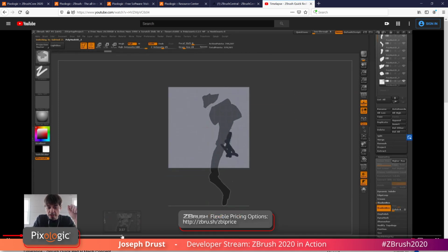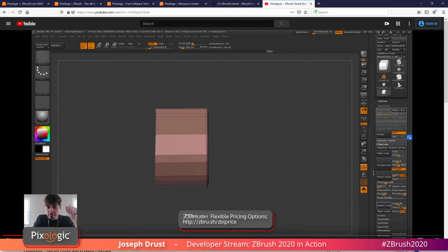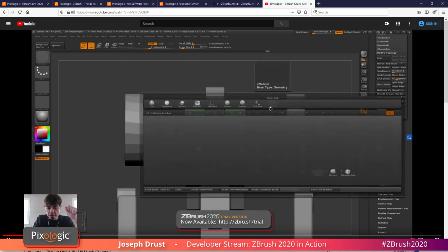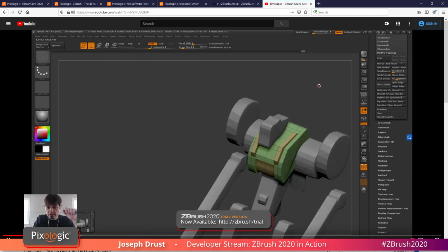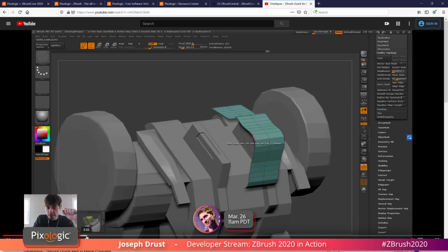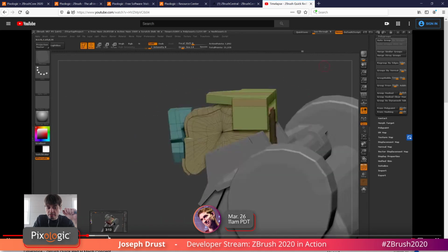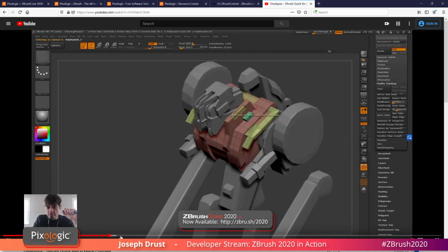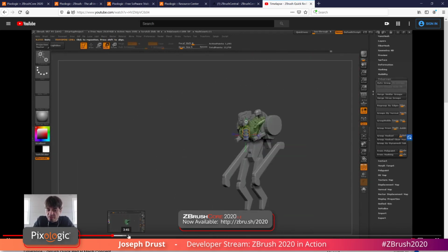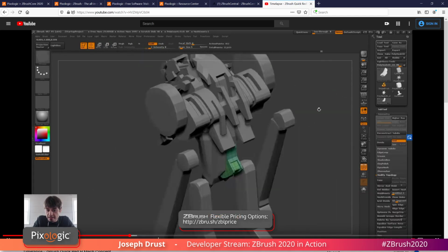And then after all these are drawn, come through and clean them up. We made a macro today to do this, to clean up those different forms. So it's just a time lapse of the process here. And then after those forms are cleaned up, I went through and started using ZModeler to add some more interesting items, just different ZModeler processes. And then the mesh itself ends up getting the dynamic and the QGrid options on it to smooth out the processes. You can use that crease option with 45 degrees and then add the smoothing to it.